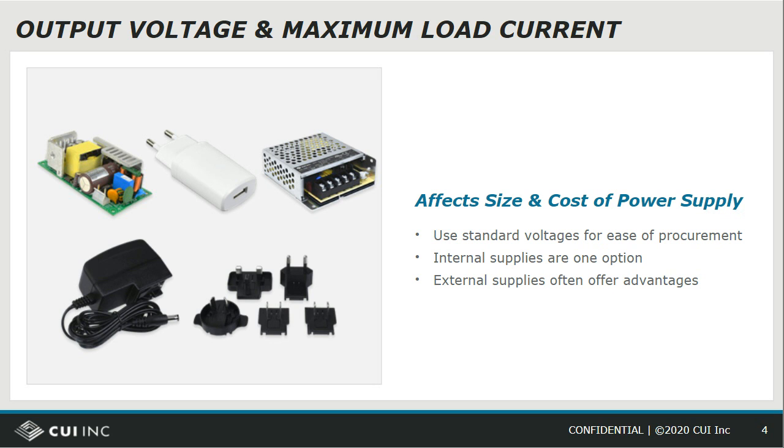They will probably be more readily available in stock already. And if you need some other voltage for part of your supply or your product, you can use a DC-DC voltage regulator to create the custom voltages. The difference between selecting an internal and an external supply regarding the applied voltage is that an internal supply generally will be able to provide a tighter voltage tolerance.